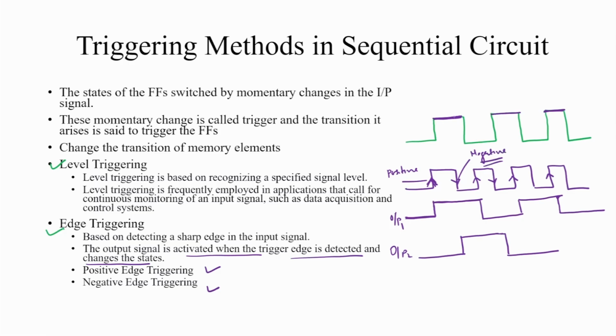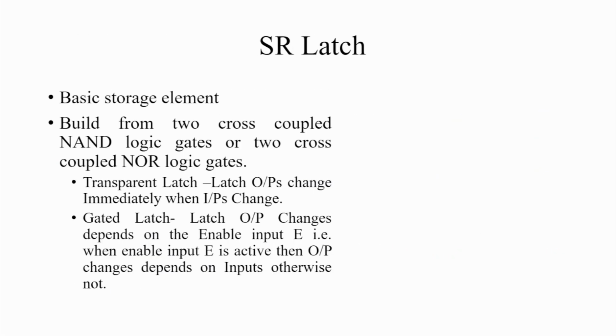This is known as, and these are what? Latches are level triggered, and flip flops are synchronous sequential circuits which are edge triggered. So, generally first we start with the SR latch. SR simply represents set reset latch.